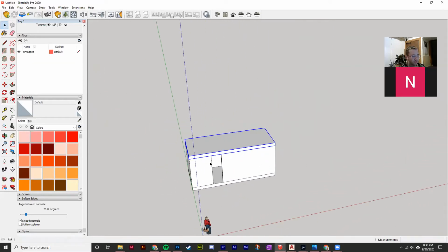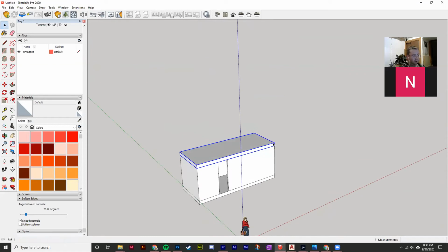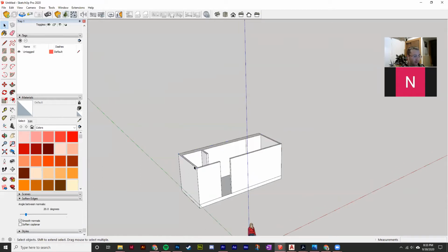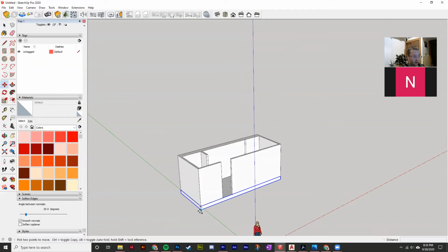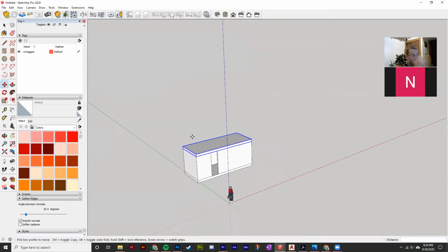This is also really useful. You can array commands, or you can duplicate them. So for example, if I was doing a skyscraper, and I knew, okay, all of my floors are 10 feet and there's 10 of them. So I can click here and then here. And you can see in the bottom right corner, my distance is 11. And then I can click. And then if I want to multiply that by 10, I'm typing X 10, and you can see that pop up in the distance. And then if I hit enter,